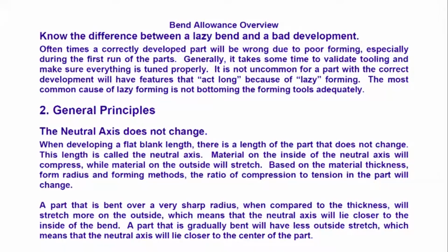It takes some time to validate tooling and make sure everything is tuned properly. Not uncommon, but a part with the correct development will have features that act long because of lazy forming. The most common cause is not bottoming the forming tools adequately. Eventually, they will tell you about what is bottoming, what is coining, what is air bending, three things.